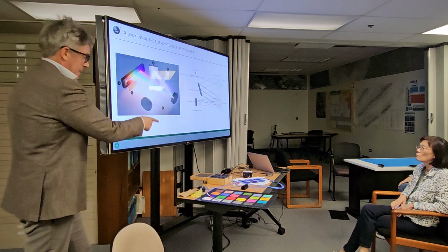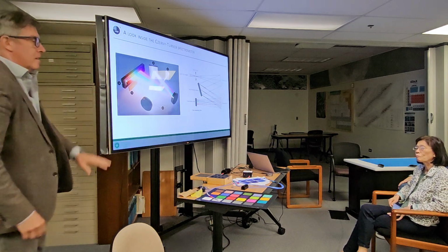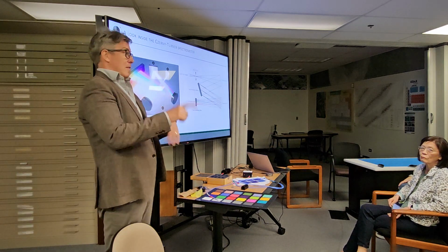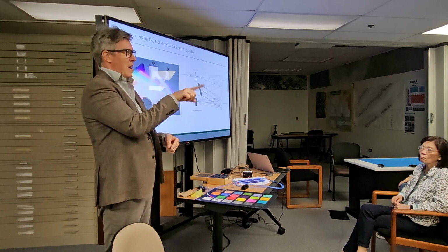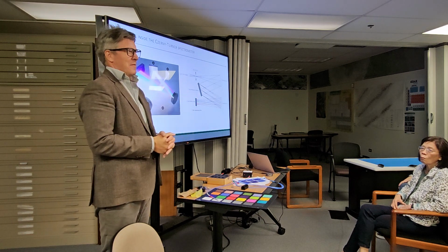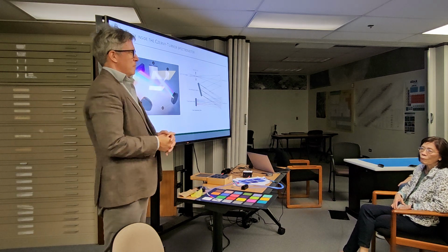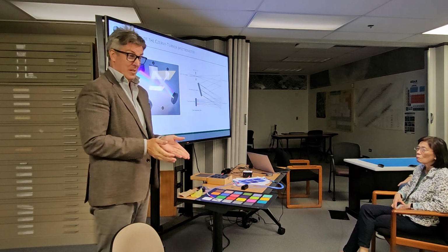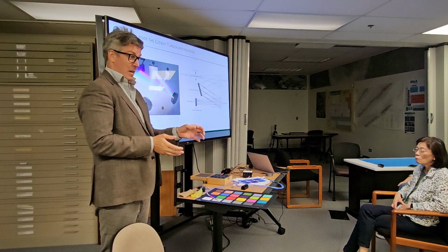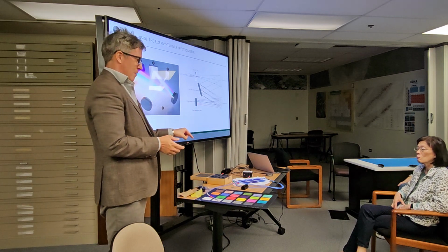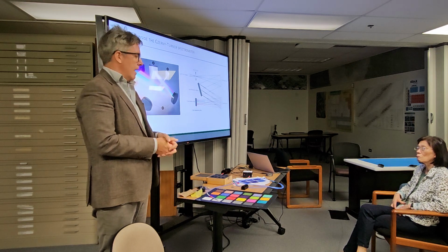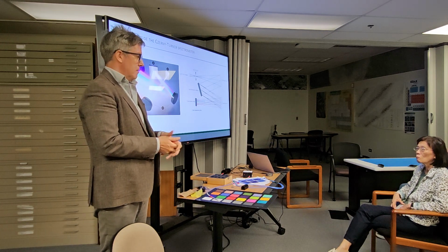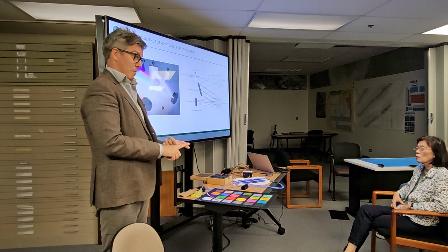The difference between a CCD and a CMOS is, you remember I said, we're generating this flux of photoelectrons, and the bias voltage is whizzing them around. We're converting photons to photoelectrons, and we've got to assess what the charge is, because we're filling that bucket. Remember, beneath every pixel in the array, we have a silicon integrated circuit. That circuit basically comprises a transistor and a capacitor, a gate and a bucket.